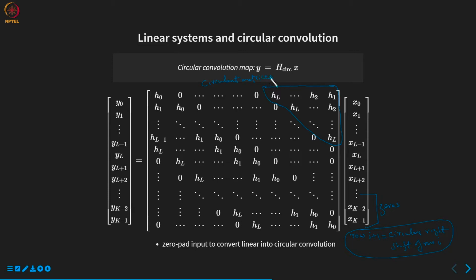And we see that just because we had an LTI system, okay, and just because we had that convolution operation describing the output for a given input, and we were able to look at a finite number of symbols, finite number of signal points, right, up to capital K, and that was under our control. We could zero pad or do something like that. We are able to get a circulant matrix to represent the input-output operation. Okay, from input to output, the operator that's working on it can be made a circulant matrix.